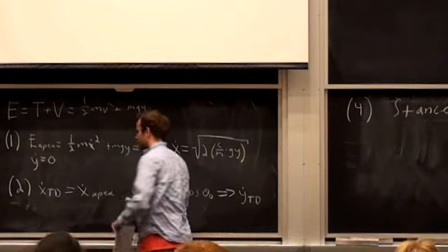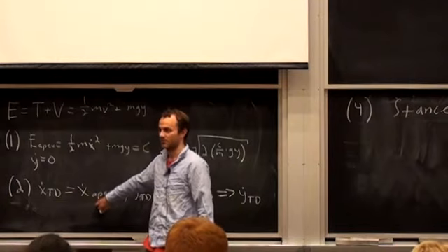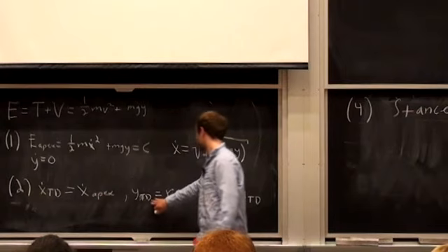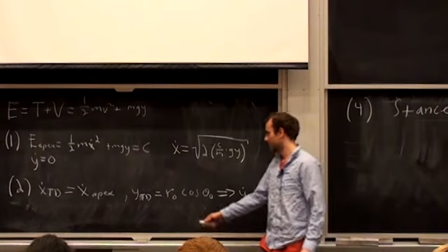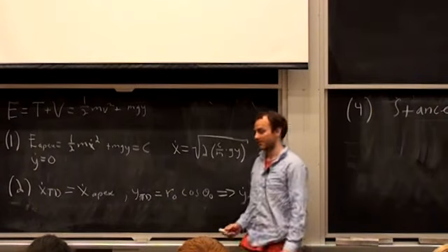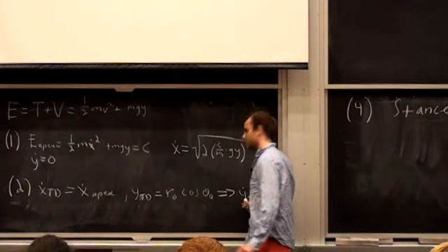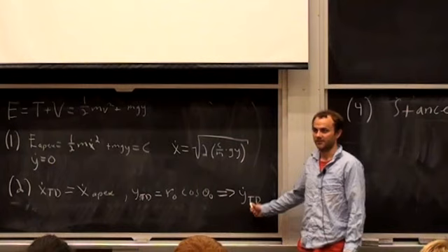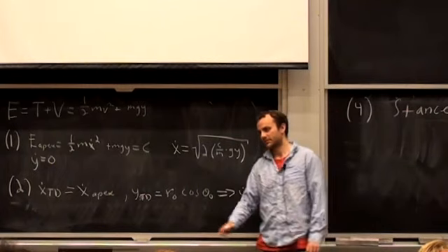Sorry. So to get to 2, to get this falling phase, x doesn't change. There's no forces in the x direction. Y touchdown, you fix this angle. That's the instantaneous warp of the leg. So when it touches down, it's going to be this high, because that's when touchdown is defined, when the toe hits the ground. And then here you know your height, and again, conservation of energy will give you the y dot touchdown. Right? And so that just allows you to figure out your state when you come in.